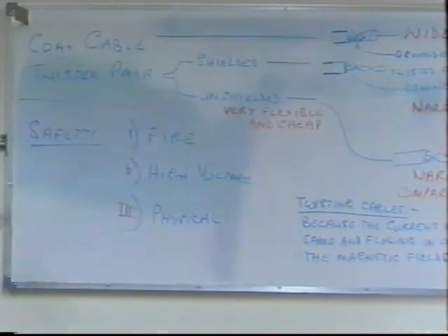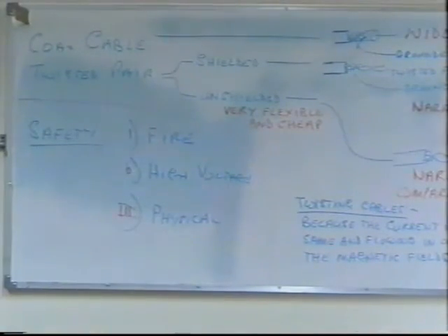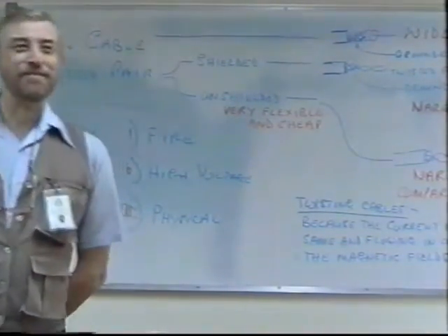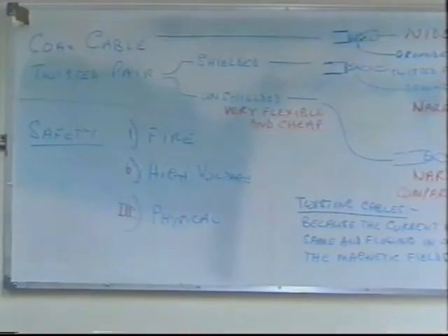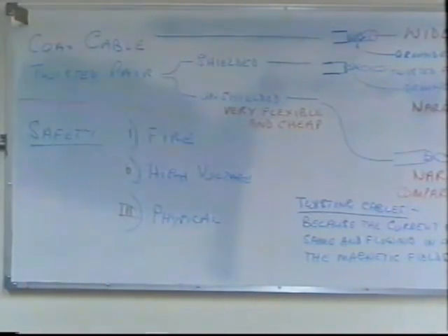Whenever you're dealing with these high voltages, I know the procedure in the Royal used to be you must always work in pairs, two of you at a time. One guy goes and does the job, and the other guy stands back. In case he gets the electric shock. The idea being that if the guy gets an electric shock, the other guy can do something about it. They should shut off the power, that's the first thing. He's supposed to stand by the switch.